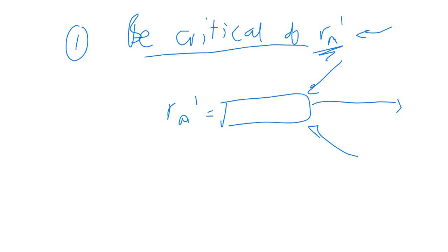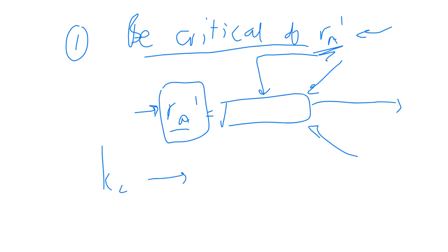Be critical in the way that the rate expression was derived. Did the researcher, the author of that paper, prove that it was free of external diffusion effects so that I can apply it as is in my reactor? Note, Kc is not translatable from one reactor to another.